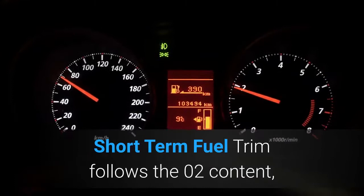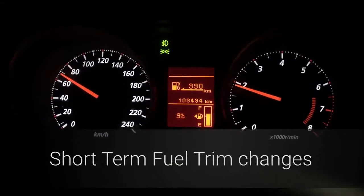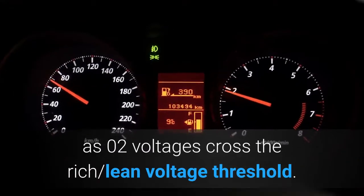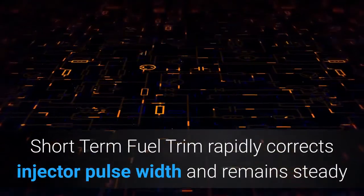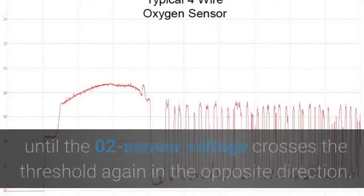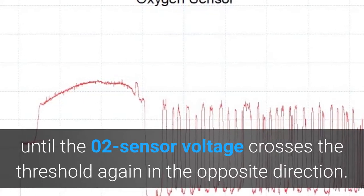Short-term fuel trim follows the O2 content. Short-term fuel trim changes as O2 voltages cross the rich, lean voltage threshold. Once O2 voltages cross this threshold, short-term fuel trim rapidly corrects injector pulse width and remains steady until the O2 sensor voltage crosses the threshold again in the opposite direction.